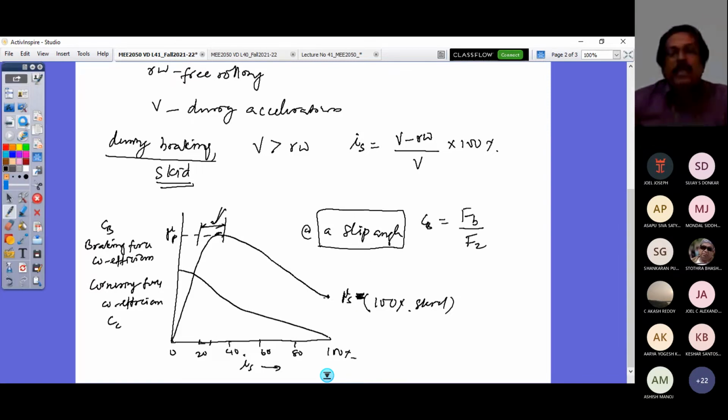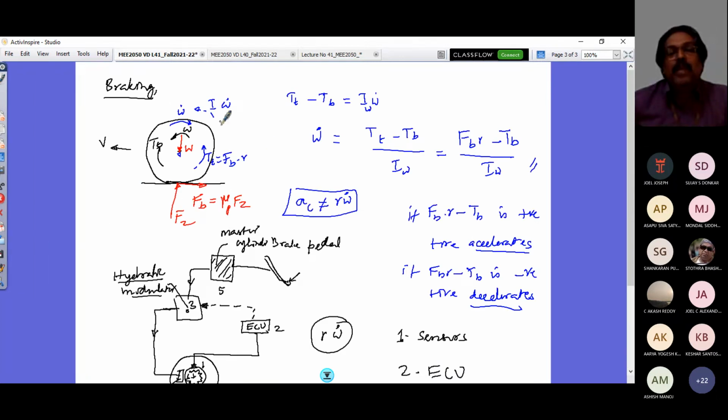And also we have looked at the tire dynamics during that time. As the braking torque is applied because of the cylinder pressure in the wheel, you get your braking effort developed at the wheel, and that braking effort into the radius is the tire wheel moment. If this difference is positive, then the wheel is still not decelerating. If this difference is negative, then it is decelerating. So you apply your braking torque to ensure the condition of deceleration, and that would be happening here.